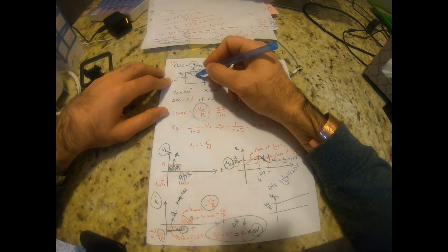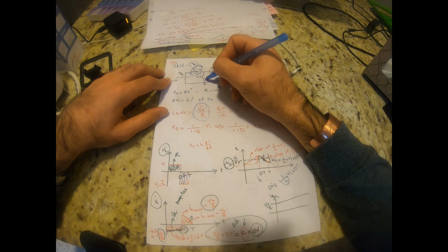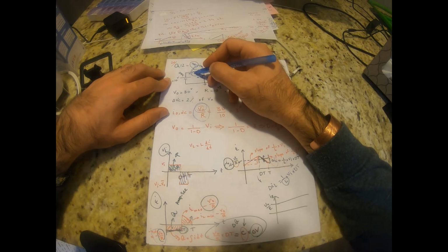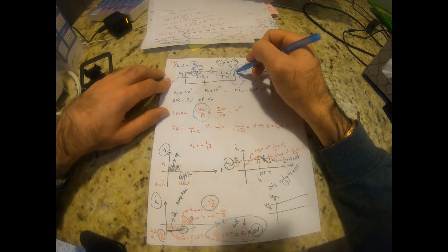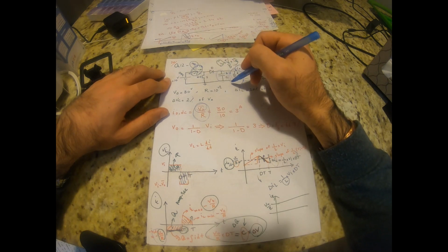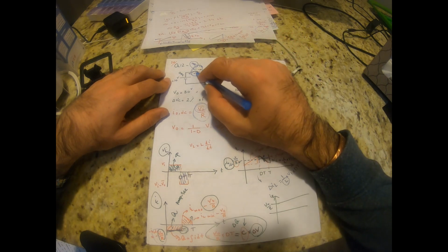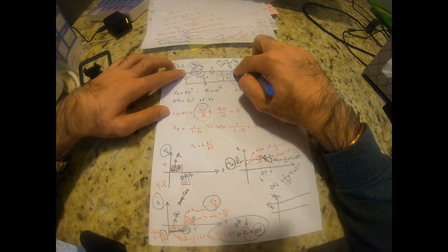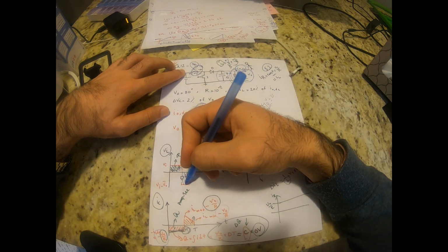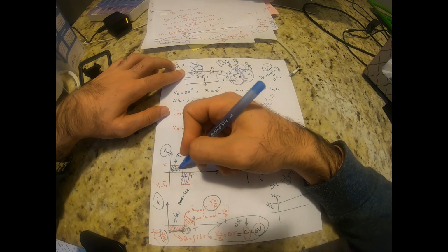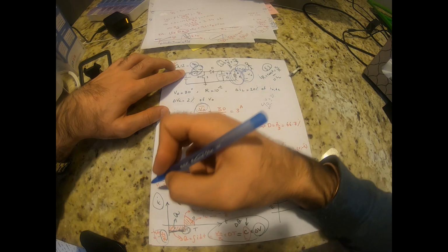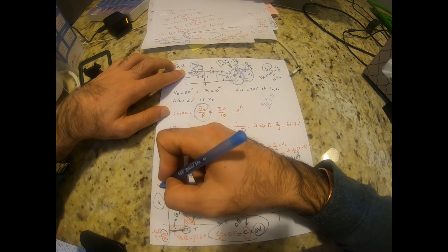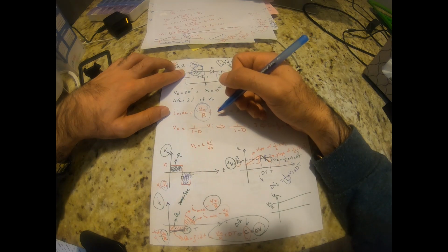When the switch is off, the diode is not going to be on because the inductor has some stored energy. It's going to keep the diode open, and we have an RC circuit at the end. Our inductor voltage is going to be VI minus VO, so this is what we have. Because of the volt-second balance, these two areas have to be equal, so this definitely has to be negative. That shows that VO has to be bigger than VI.